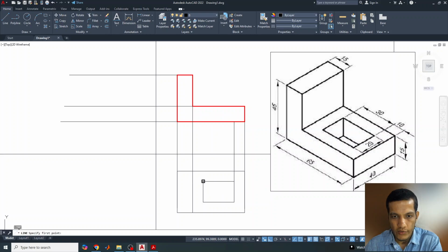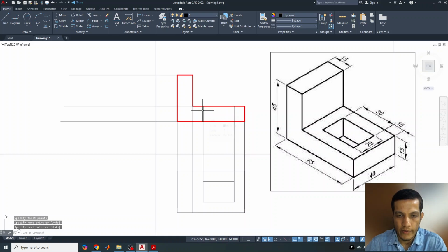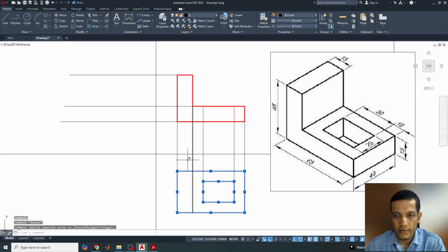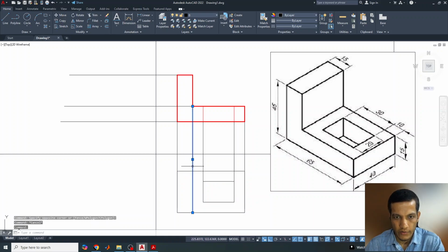which is there in this object cannot be visible from the front view, so that needs to be drawn as a dash line. Okay, these two lines we can draw as a dash line. I can change this color also. Okay, we'll draw the dash line later. Now presently you can see this view is there, and one more line will be there also.